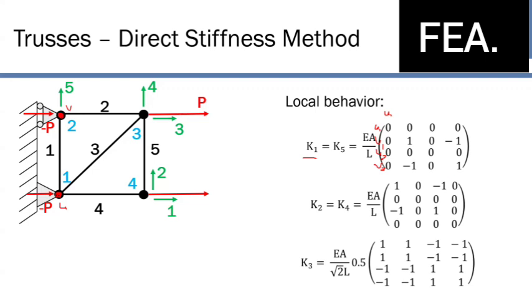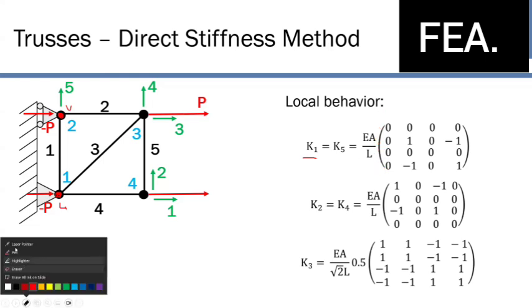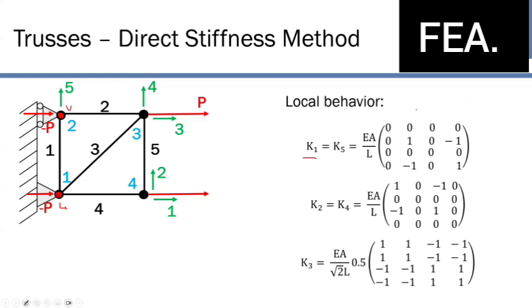Sorry, do you mind just re-explaining that? Yeah. So basically what each row represents, if we think about the rows in each matrix, it's the relation between the force and the displacement. So in row one, where we have it restricted basically, the pin support can't move across, there's not going to be any force and there's not going to be any displacement, right? So our stiffness matrix is going to be zero there. The second one, our roller is unrestricted in that dimension. So what we're going to get is that it can move in that direction, essentially.